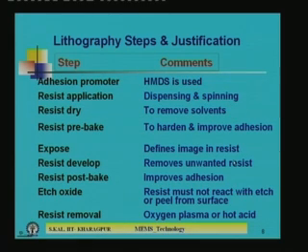Non-uniform thickness of the photoresist will lead to non-uniform structure appearance on the surface after development. In some cases the structure will be much more prominent, in some cases it is not prominent.